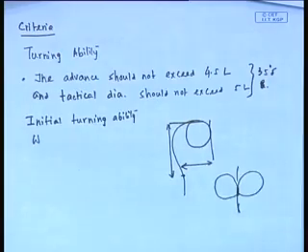Remember that the forces depend on the hull shape. Hull shape is purely symmetric. The answer is in the propeller. Remember, the rudder is behind a propeller, and the propeller is a single screw propeller. Propeller has asymmetry. It is moving in one direction. So the flow has slight asymmetry on one side.